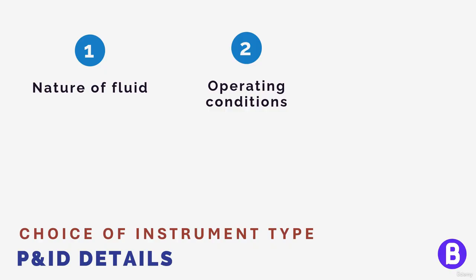The required range we want to measure. So if we want to measure readings where the ratio between maximum and minimum reading is 2 to 1, for example, this is a different case from measuring the range with a ratio of 5 to 1. So the minimum parameter, for example, the flow is 1000 and the maximum is 5000. This may be greater range and maybe not all types of flow elements shall fit for this range. If it is 10 to 1, then there will be very few types that may accept this range. So this is a very important factor when determining the type of the instrument.